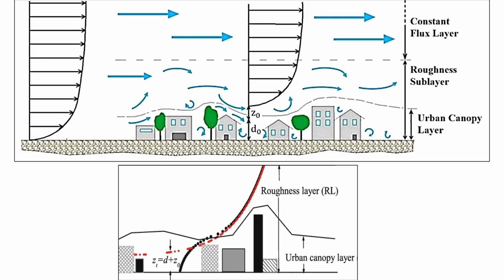So if there are no obstacles near the ground like a building, tree, etc., there is no Z0, that is there is no urban boundary layer formation. Okay, so there is no Z0, D and so on. If it is there, then these two layers will be added. So mostly we will discuss these two kinds of velocity profile. One is without the obstacles, another one is with obstacles. These two profiles we will discuss further.